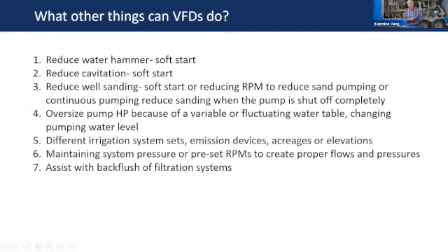I've seen it help with reduced well sanding. If you have a deep well that's producing a lot of sand as you're pumping, maybe especially when you shut it off completely. I've had wells like this before. When you first start them up after they've been shut off for a couple of days or something, man, they pump a lot of sand for a few minutes. And then you've got filters plugged and all kinds of problems. You've got to flush and go crazy. If you can soft start it, sometimes that'll reduce some of the sand.